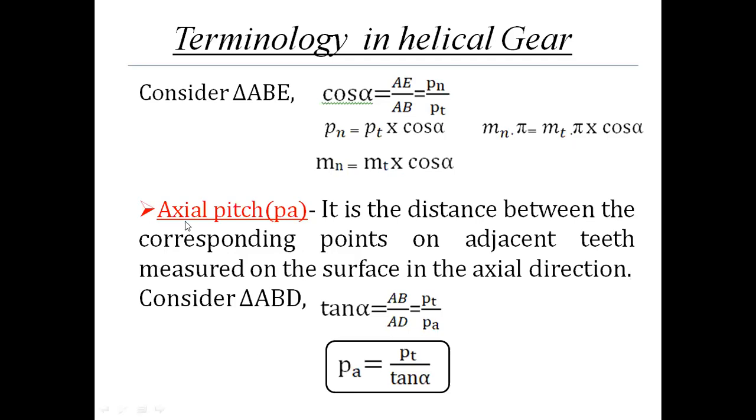Now, the third one is axial pitch, denoted by P suffix A. Axial pitch is Pa. It is the distance between the corresponding points on adjacent teeth measured on the surface in the axial direction.